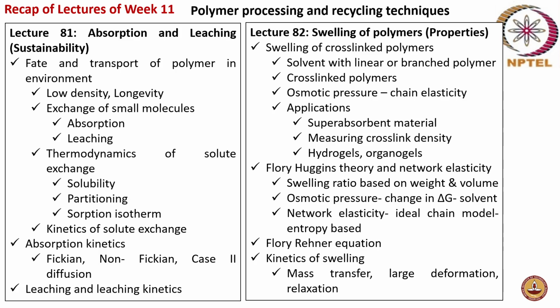Okay, and then measurement of crosslink density, and then hydrogels and organogels. So hydrogels means the solvent that is taken up by the cross-linked polymer network is water, or aqueous based solvents like your salt solution, whereas organogels means organic solvents. Okay, and then Flory-Huggins theory and network elasticity. So how is swelling ratio based on weight and volume?